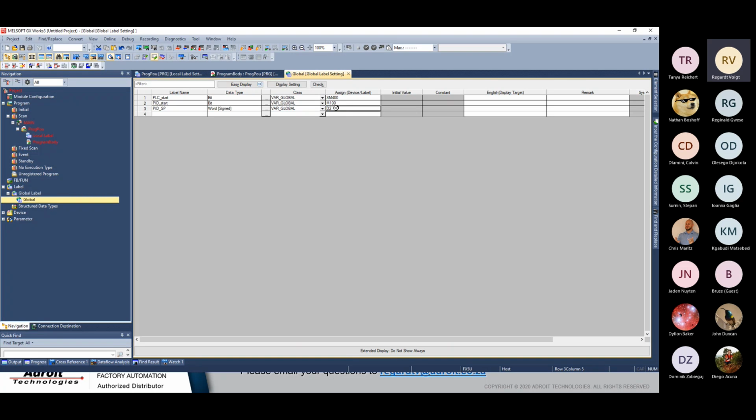Another thing to keep in mind here is if you're using an HMI, like a GOT or a SCADA, you can also use a D address, because it means the operator using the SCADA in the plant will set the set points. If you have a potentiometer which sets the set points, then you have an analog input card. Just as an example.